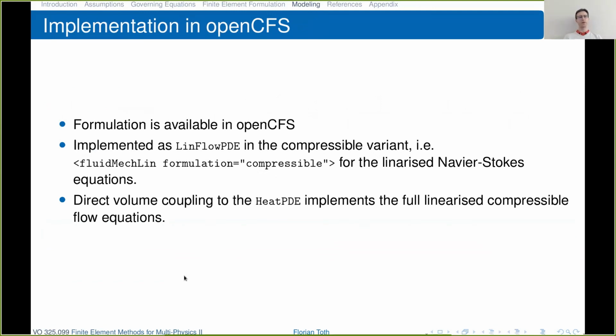So finally, the implementation I presented here is implemented in openCFS, and it is called LinFlow PDE. In the input scheme, the tag is fluidMechLin, and be aware that this formulation is implemented in several forms. One is for the compressible linearized Navier-Stokes equations. There's also an incompressible variant in the same PDE. And if you want to take the heat conduction into account, this is implemented as a direct volume coupling to the heat partial differential equation, so the heat PDE that you already know. Together, the implementation is for the full linearized compressible flow equations.